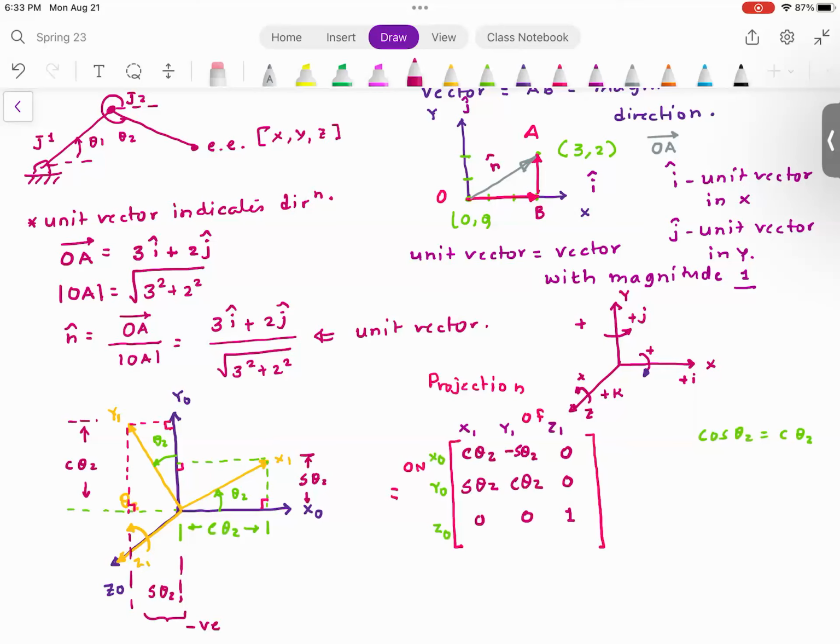But DH parameter has limitations. There are some configurations of robot where you cannot use DH parameters. But rotation matrices will always work, no matter what type of robot it is. Whether it's an articulated robot, a ground robot, or a UAV, aerial robot, quadcopter, rotation matrix always works. So rotation matrix is the technique of choice, and I want you to understand this.